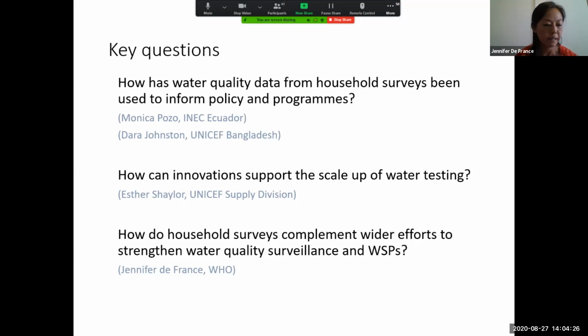And second, related to testing, I think everyone knows this, but just to remind everyone, for programming, for ensuring water quality, we should rely on other tests besides E. coli. There are cheaper, simpler tests that we shouldn't forget about, such as, if you're disinfecting water, making sure there's adequate chlorine residual, turbidity and pH for looking at effectiveness of disinfection. So just flagging that. Thank you.